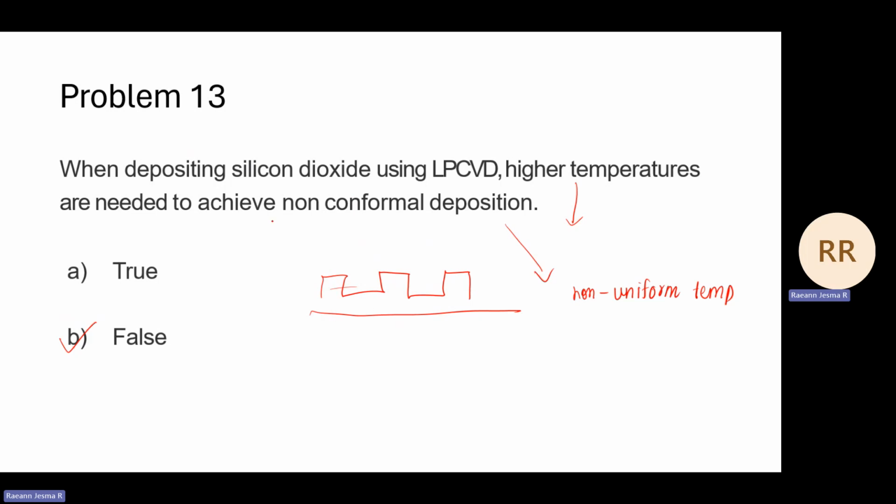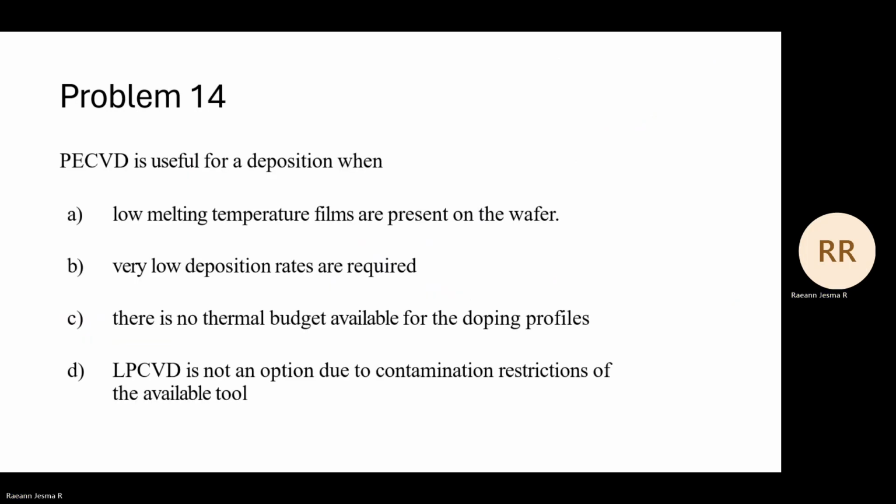And that's why in the case of LPCVD, instead of just heating the susceptor inside a quartz chamber, they'll heat the entire quartz chamber so that there will be uniformity in the temperature. Okay. Is this clear? Okay. We'll move on to the next question.